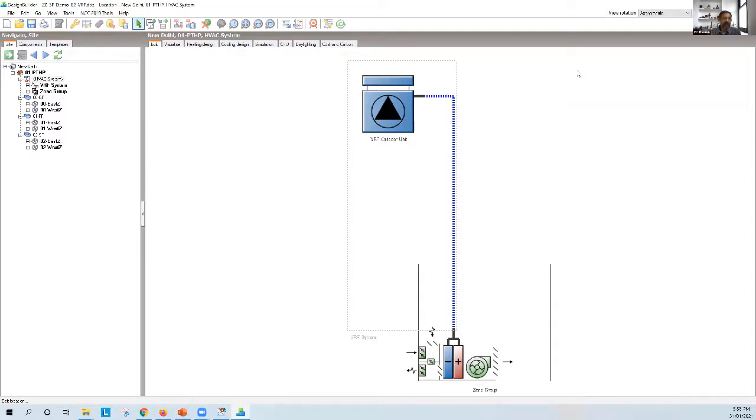Okay, and unfortunately, due to global warming, we're getting to the point where we're beginning to hit 45 degrees plus in some situations, and when that happens, some of these air-cooled condensers really struggle. Okay, so something to be very aware of. Is there a solution for that?